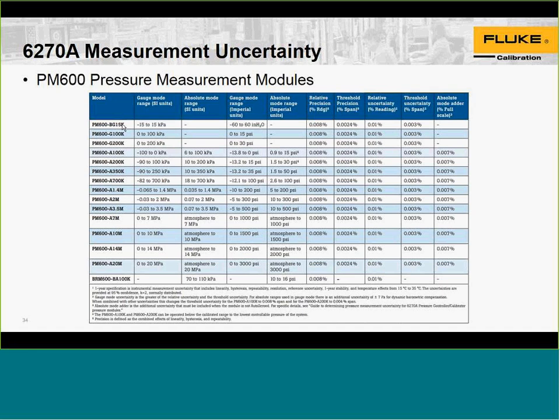So I think Josh explained earlier that typically you will purge an instrument or flush the fluid out of it, assuming that the fluids are compatible. Typically, measurement performance will not be highly dependent on which type of fluid, other than that head correction.